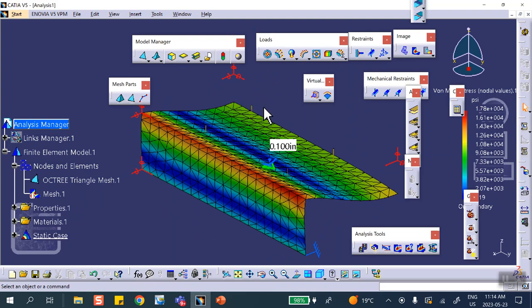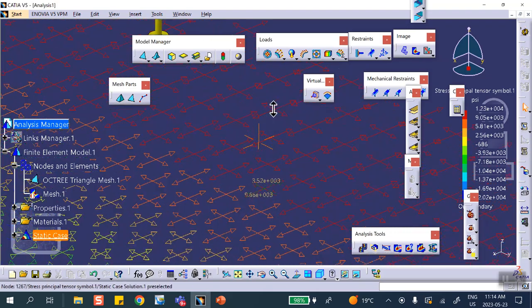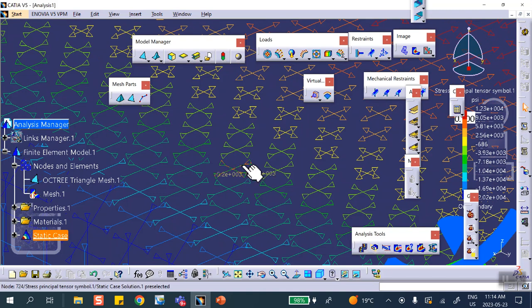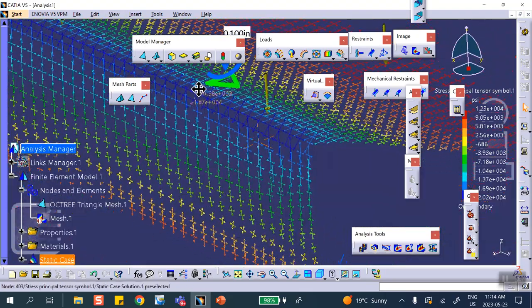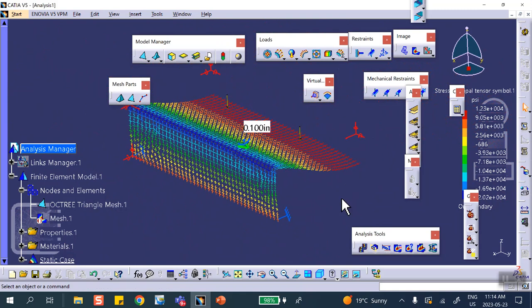Okay, all right. And once again, if you look at the principal stress right here, notice that depending on what point you look at, it gives you the arrows, two of them, in-plane principal stresses, because the out-of-plane one is 0. That's the assumption in the shell theory. Okay, stress through the thickness is 0, thin shell theory. Okay, good.